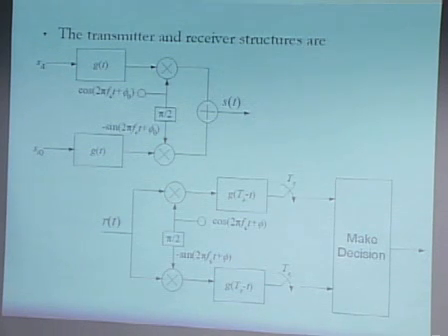So there is another degree of synchronization, which is in time. So we want to sample here every T sub S, every symbol time. So we want to make sure that the sampling points are aligned with the right points on the transmitter. So this requires time synchronization, which is also achieved with pretty high accuracy. And in the book, there's a section on this. If any of you is interested, you can read it, but it is optional material.